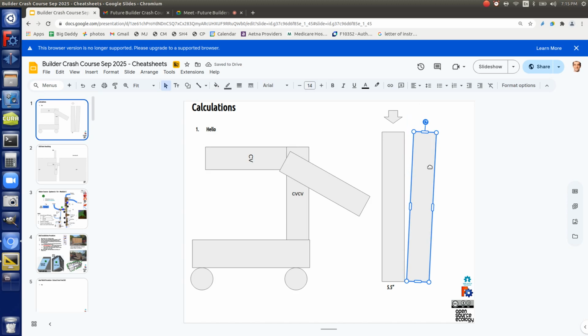Okay, if you look at the force diagram on that, here's how you do a force diagram. Assume the force acts in the middle of it. Cool. In theoretical force diagrams, the middle of the material, there's a load on top of this wall module. For analysis, one good assumption is that the force acts in the middle of something, because it's kind of true. If it's spreading its weight over the entire thing, it's like having one force in the middle. Okay.